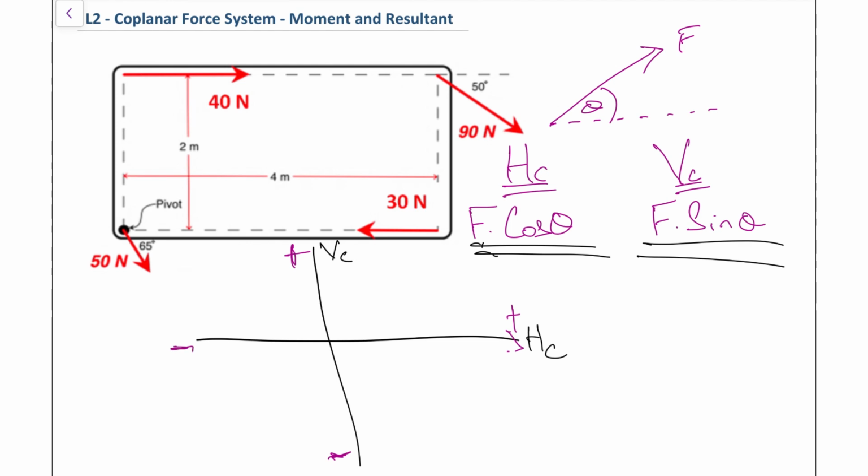And as a standard rule of thumb, when I put the plus or minus, what that should mean for you is the top value is our horizontal component, bottom value our vertical component, just like we do with vectors. So let's say we have a force going up and to the right. In this quadrant, both our components will be positive. If the force is going up and to the right, it means our horizontal component is positive, and also our vertical component, because it's going up.